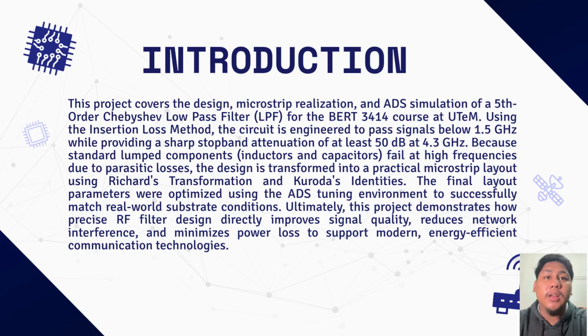At high frequency, standard lumped components like inductors and capacitors fail due to parasitic effects. So we transform our design into a practical microstrip layout using two key techniques, Richards transformation and Kuroda identities. We then optimize the final layout parameters using the ADS tuning environment to match real-world substrate conditions. Ultimately, this project demonstrates how precise RF filter design directly improves signal quality, reduces network interference, and minimizes power loss to support modern